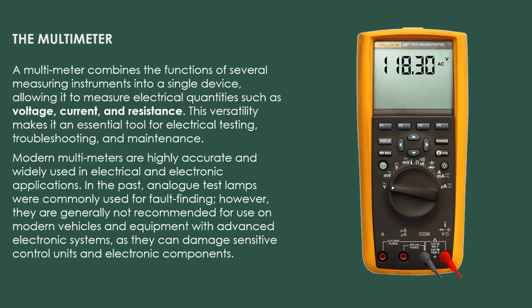In the past, analog test lamps were commonly used for fault finding. However, they are generally not recommended for use on modern vehicles and equipment with advanced electronic systems, as they can damage sensitive control units and electronic components.